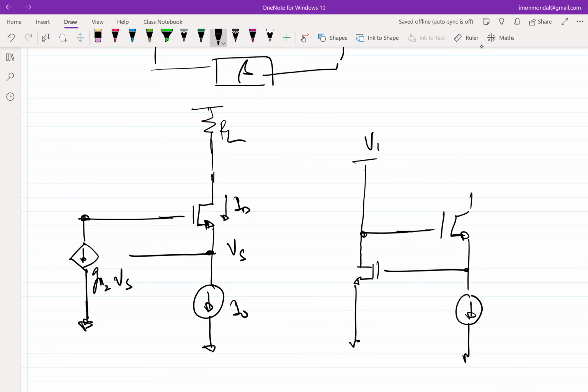So now obviously I cannot connect this to VDD because then there is no negative feedback, right? Because the gate of M1 then stays put at VDD, but I want gain between these 2 points, which means I can replace this with some R2 and I can have RL here. Okay. So this is another way of biasing my circuit, another way of setting up your negative feedback.